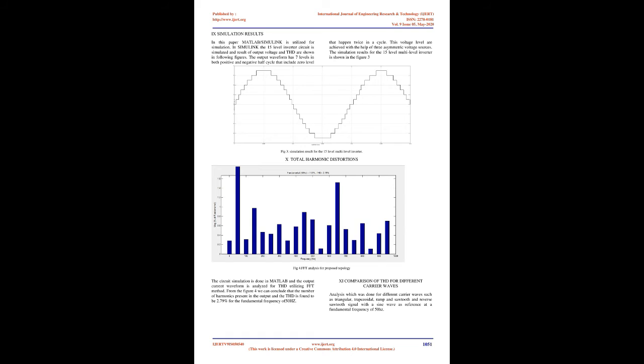The voltage stress across each switch is given below. S1: V1 plus V2, S2: V1 plus V2, S3, S11: V3, S4: V2 plus V3, S5, S12: V2 plus V3, S6, S13: V1 plus V3, S7: V3, S8: V3, S9: V1 plus V2, S10: V1 plus V2 plus V3.